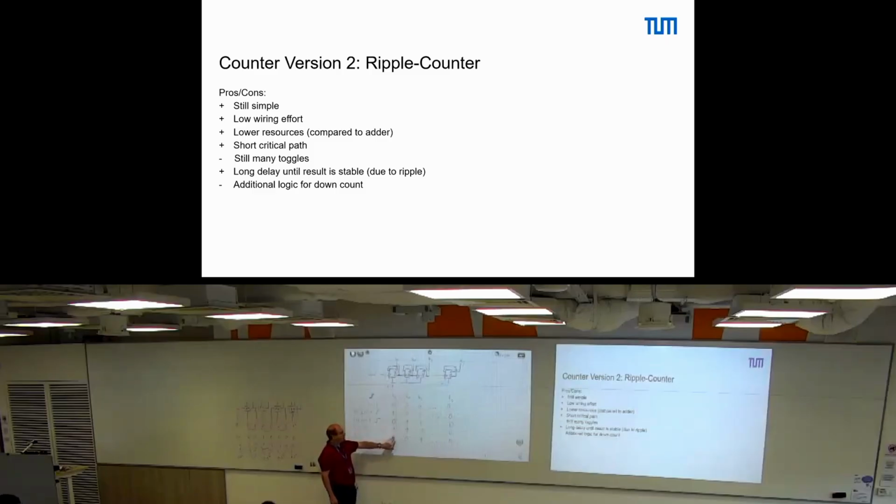The first flip-flop might already be 0, the second is also 0, the third one is still 0, because the one did not yet really flip. So it is super fast in terms of counting high-speed events, but I cannot immediately compare to a reference, which makes it suitable only for specific applications. Okay.